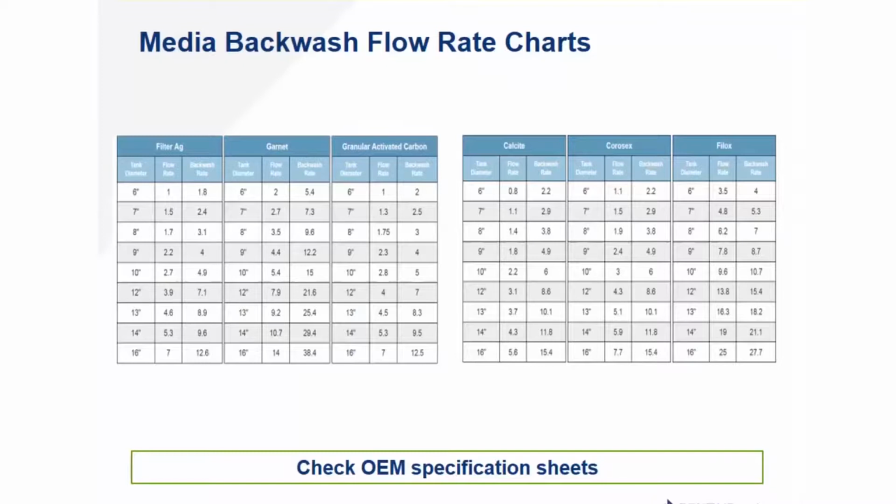So there are charts available, not only from OEM media manufacturers, but there are charts available for resources all over the place online. And you can see, based on tank diameter, the flow rate you're going to need and the backwash flow rate. This is the service flow rate, backwash flow rate. As the media gets heavier, the greater the backwash rate. Okay.